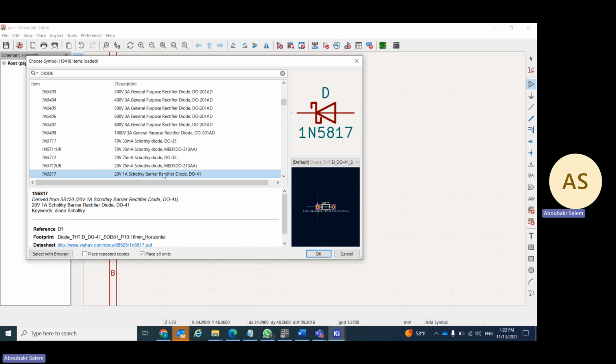We discussed the meaning of Schottky diode before, correct? So what's the difference between a Schottky diode and a regular or general purpose diode? Reverse biased, or this is Zener diode, not Schottky diode. What about the Schottky diode? Do you remember, guys? Not the voltage, the delay time, which makes this diode fast, and you can apply it for high frequency applications.